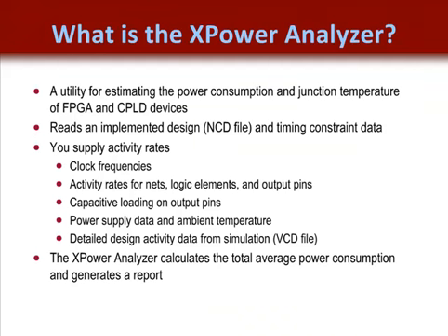A value change dump, or VCD file, is created by a simulation tool, such as Mentor Graphics ModelSim, for example. The VCD file contains information about signal or variable value changes. The VCD can be read by the Xilinx XPower Analyzer to provide accurate power estimation. Note that in order for the XPower Analyzer to match instance and net names from the VCD file to items in the NCD, that is your implementation result, the VCD file must be from a post place and route simulation.